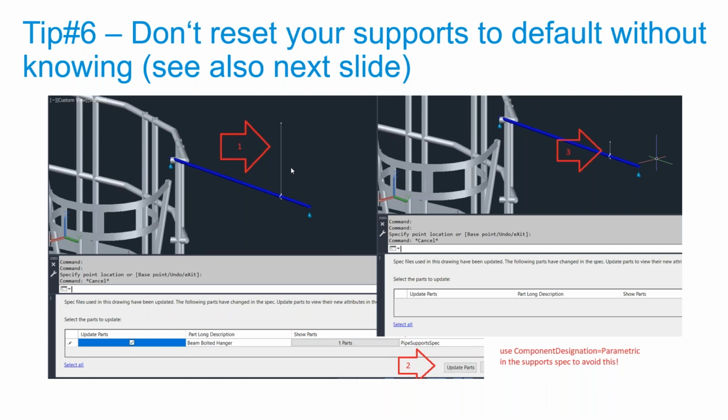And then somebody is doing the spec update, and then somebody sees, oh, my hanger needs update. So of course, let's do it. So he's doing this, and then afterwards, his hanger defaults to what it was when he originally brought it in from the tool palette. So it's totally wrong now. And this guy maybe doesn't notice and saves, and then the problem is in the world.